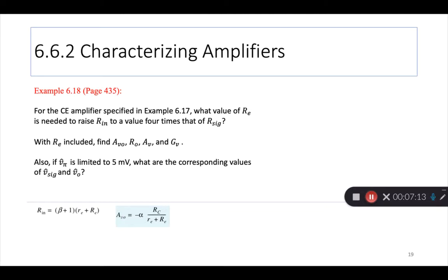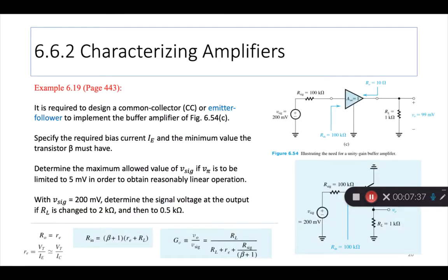If you take different transistors from the same family with different betas, they will all work in the linear range and not go into saturation, even if you have a higher V signal. So that's the advantage of a CE amplifier with a resistance in the emitter circuit.